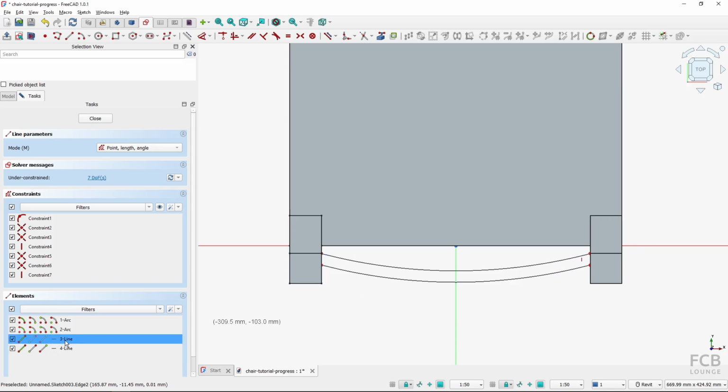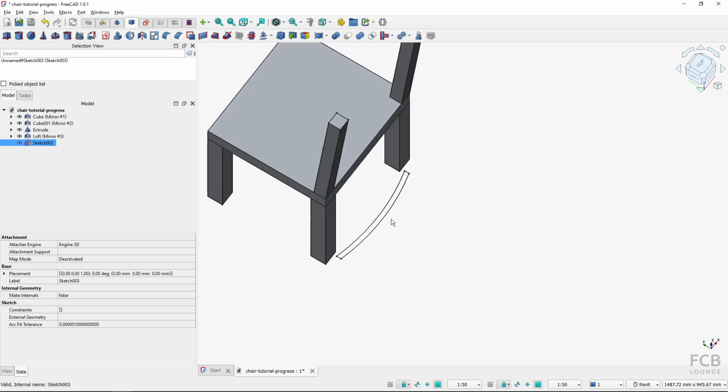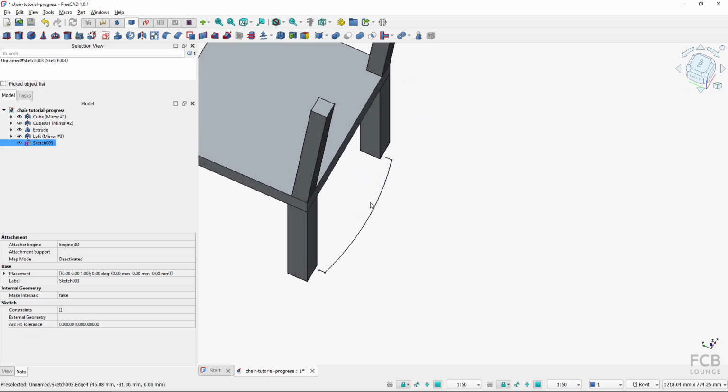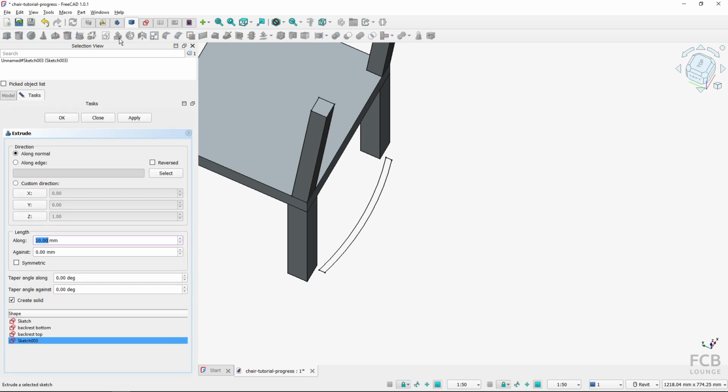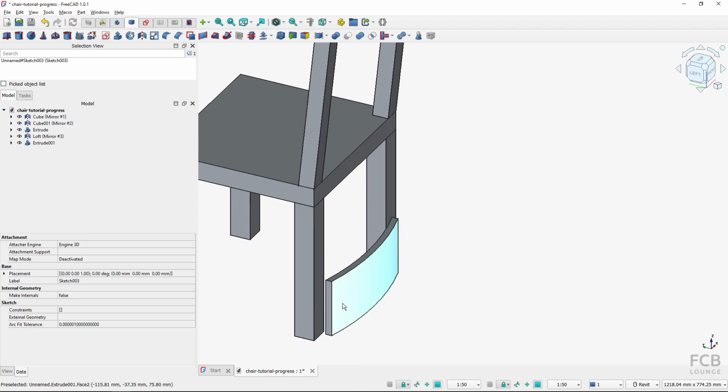So I created two lines, so the sketch is closed. So now I can close creating of the sketch, and you can see that it's created like so. It's this sketch. So again, as previously, I will create an extrusion out of it. I want to make sure that it's creating a solid, and the height will be, let's say, 150, and I will hit OK. Yep, let's say that's okay.